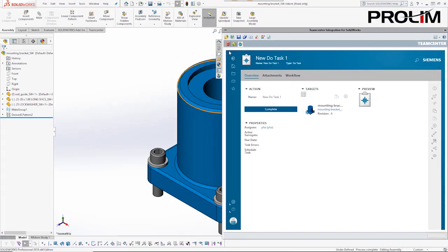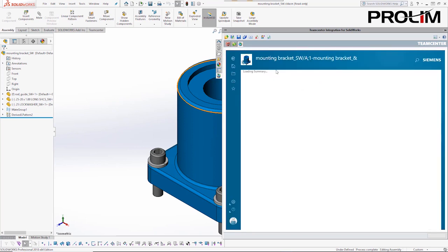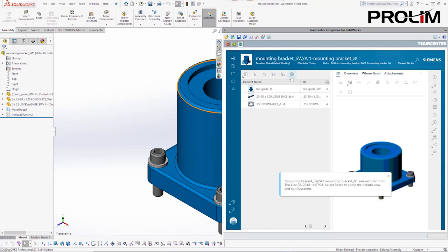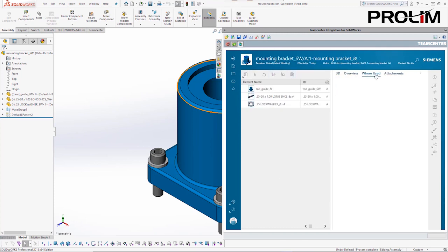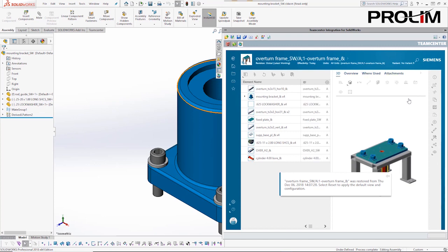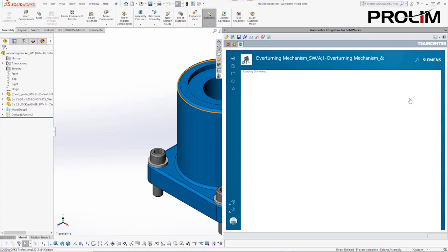He wants to make the change in a copy of the subassembly, and to update its parent assemblies to reference the copy. Hosted Active Workspace provides access to all needed PLM functionality, without ever leaving the SolidWorks session. The designer performs a where used search in Teamcenter, to find and load the top-level assembly into session, so that it is automatically modified as the target design changes.